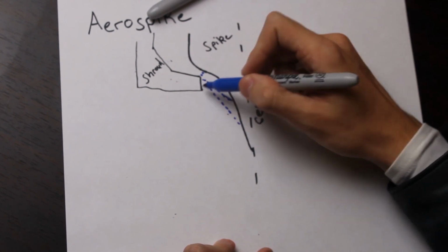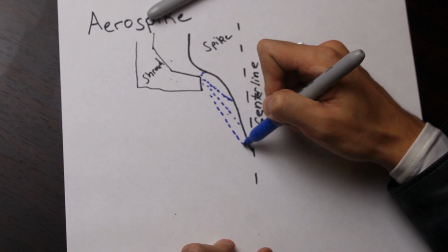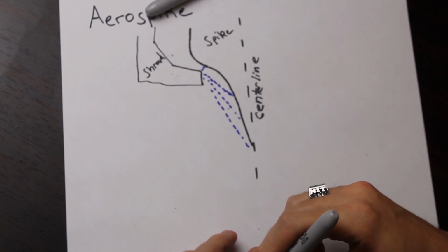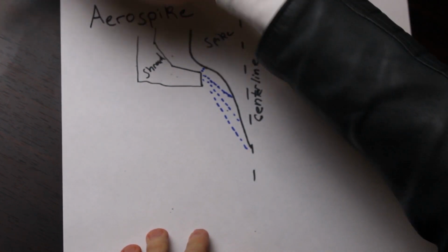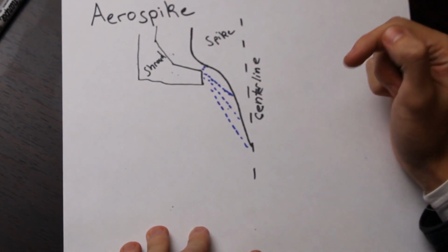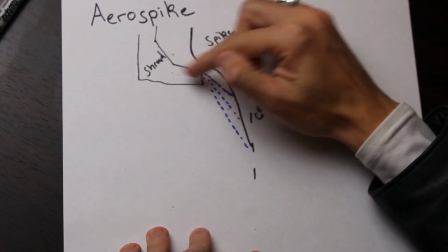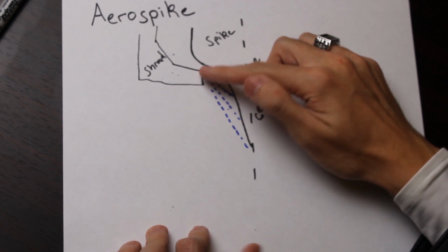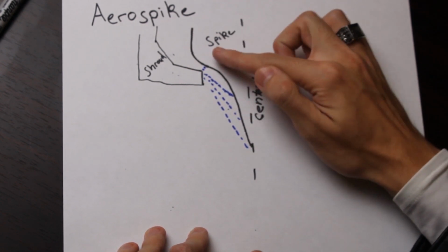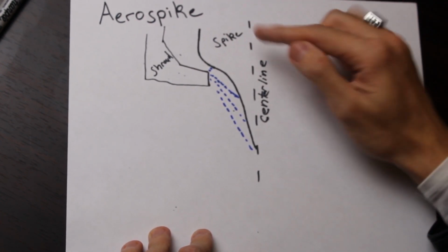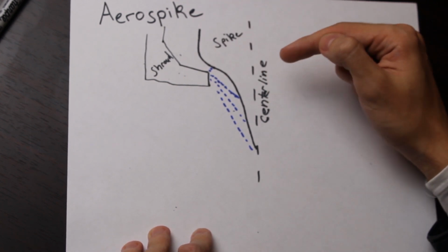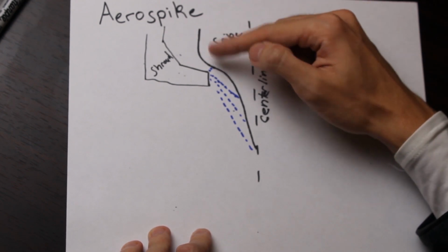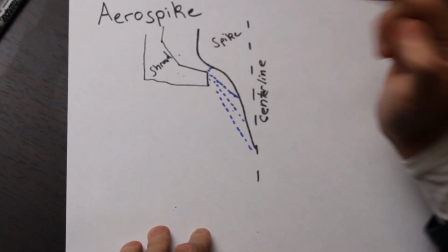We'll make that a little more obvious. Like that. And because these are characteristic lines along the Mach waves, we can calculate what the properties of the gas are along all of those. So we didn't know exactly what the shape of any of this was to start with, but by knowing that it has this geometry, what we can do is calculate where these Mach lines will intercept the shroud contour, and that'll tell us what the spike contour needs to be, knowing that the expansion fan originates at the corner of the shroud and the lines propagate out to the spike.